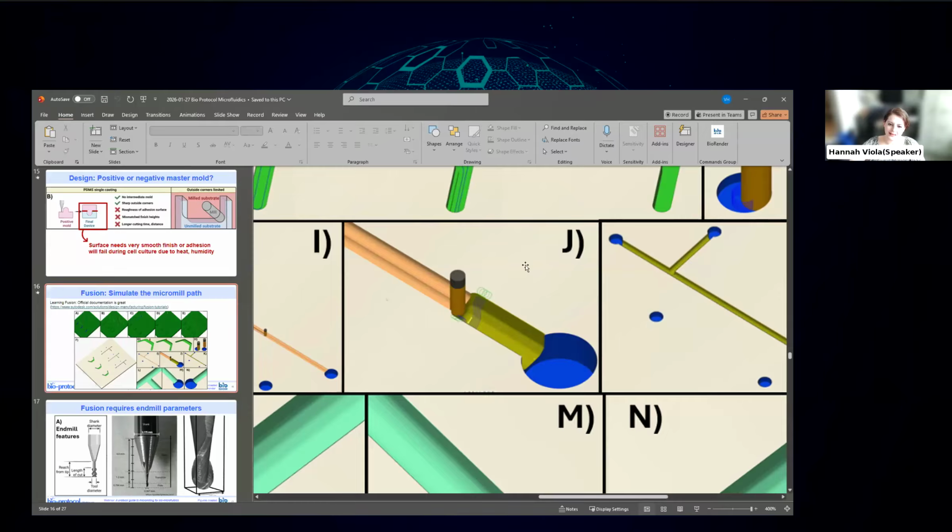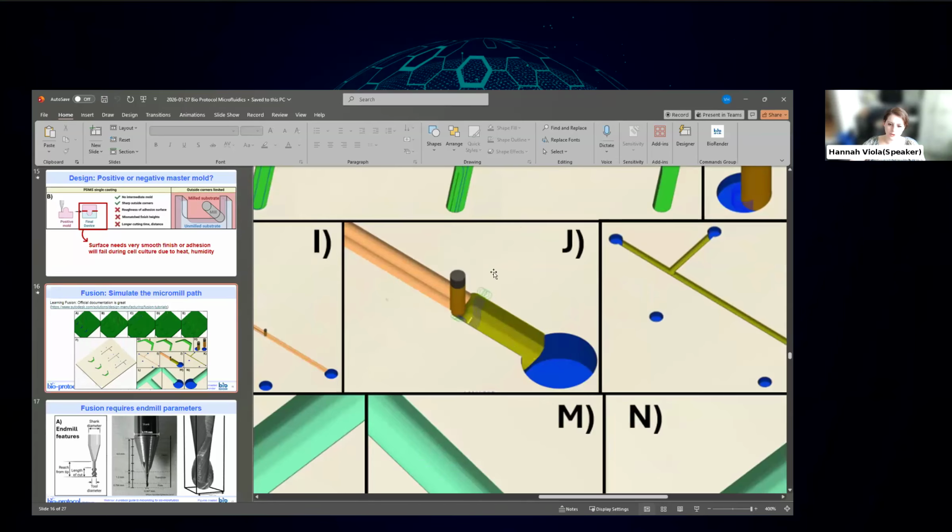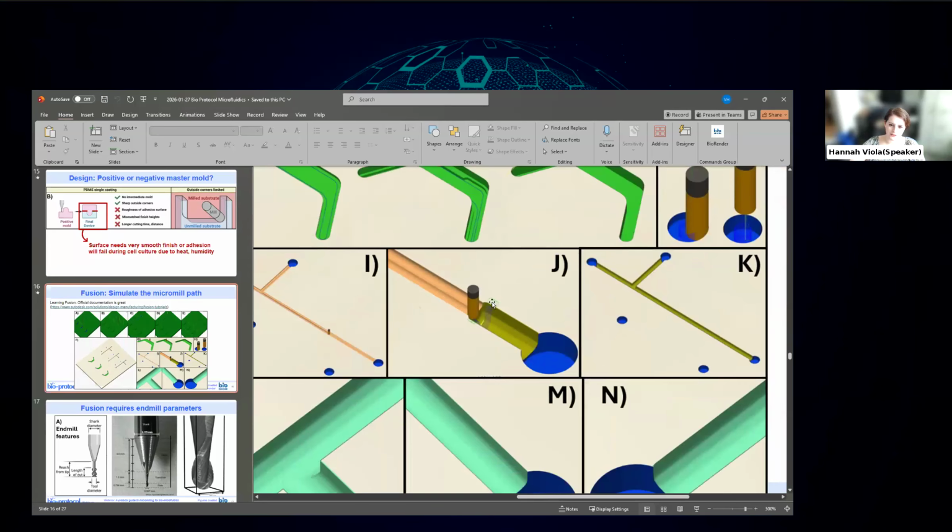I wanted to include that because if anyone's going to invest in this technique as an institution or an individual, having a ballpark of whether it's $1 million or $10,000 is useful, but it really varies a lot by the tier of machine that you get and what spindle you get, because they're sold separately, the machine itself and then the spindle and everything. They sell it part by part. But I think for most applications, you're going to be more limited by the tooltips available than necessarily by the resolution. The Z-axis resolution is going to be the same as XY.